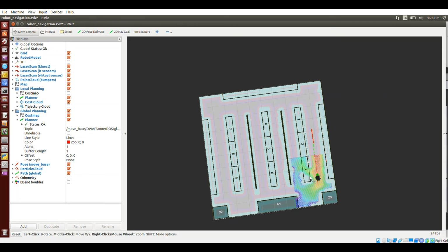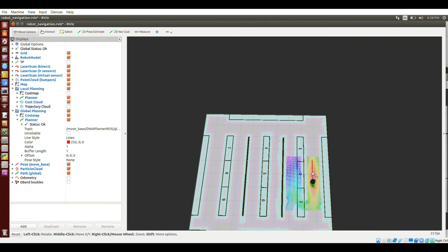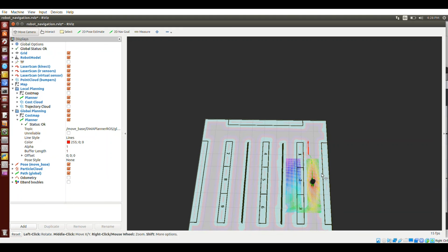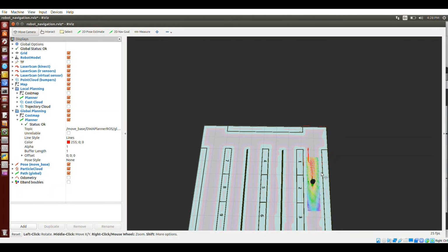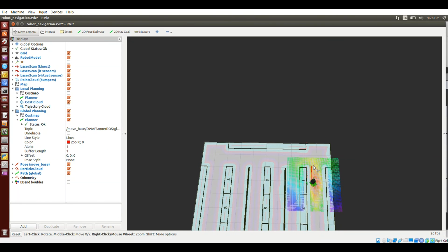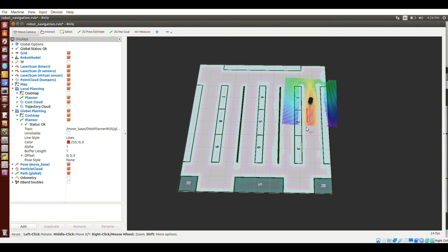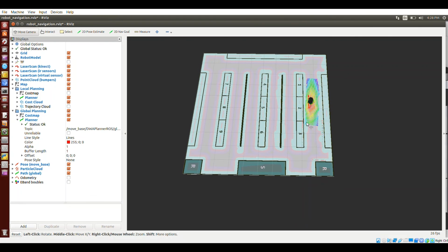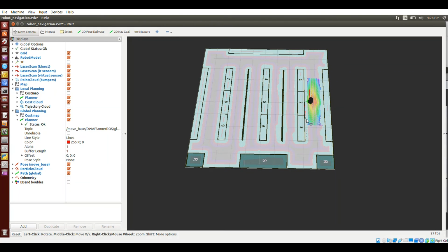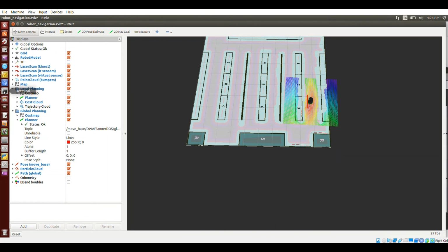Here the location was a little bit further because these lines are the walls for the robot, so if I have any point over here, the robot will not go there because it is identified as a wall. So in the future, while you are working on a project like that, you need to provide a point with XY coordinates which is not on these lines, so it has to be out of this area. Yeah, it just started to do the same stuff.